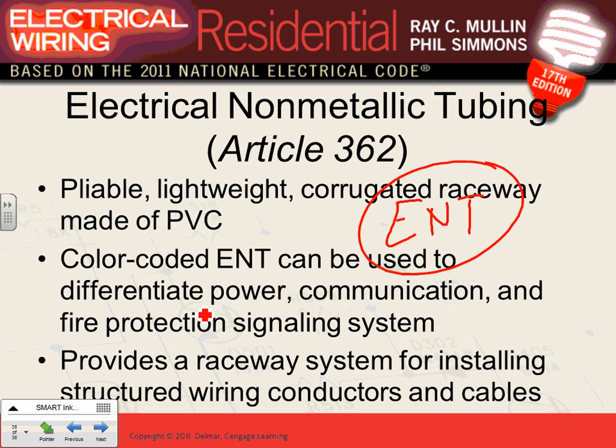If you have a highly corrosive environment, guys, you wouldn't use anything metallic. And we know why, because it rusts like crazy. Barns are notoriously famous for these locations, or any place where it's highly corrosive. Again, PVC will get you there too, but the advantage of this alternative is that it's flexible, more pliable than PVC. That's its wiring method. I don't see where we can use it in residential. I've never seen it in residential. ENT, anybody? I've seen it in dwellings.